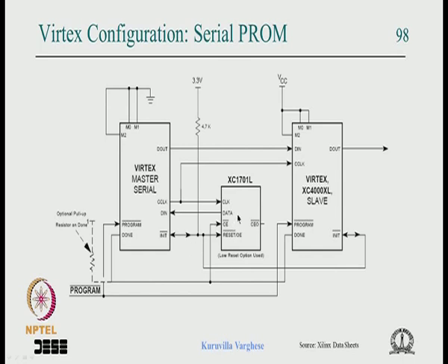And nowadays SPI or SPI based PROMs can be used. So the FPGA offers, instead of the custom serial port, an SPI port, and the SPI can work with 1-bit data, 2-bit data and 4-bit data. In addition this PROM itself can be programmed through the JTAG port permanently.